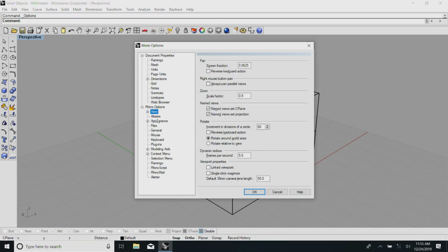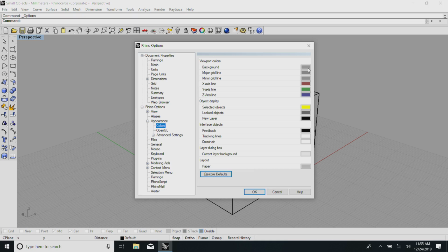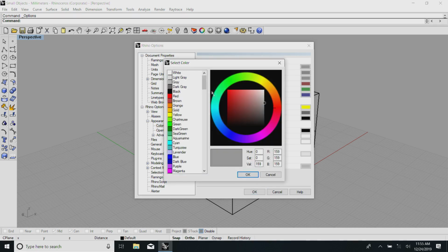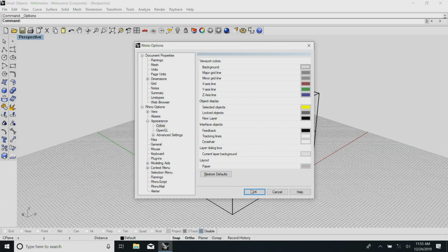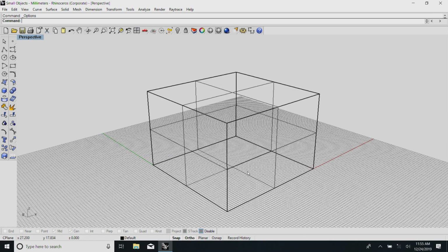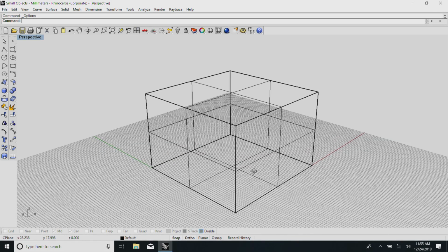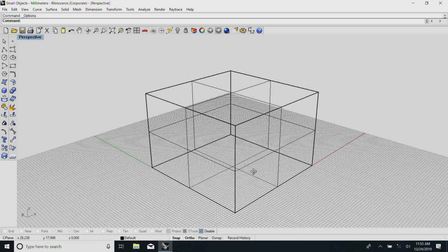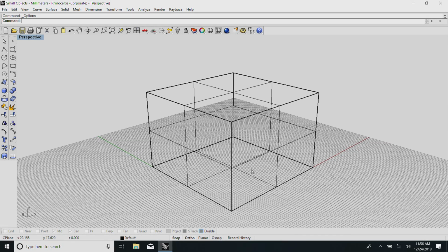The basic raw material is ready. I will just need to modify a little about the background color. Yeah, this is better. See here, this is the basic raw material with which I have started. If you dimension it, automatically whatever dimension I have picked will come there. Now, in this I need to make a 31 millimeter groove front to back.